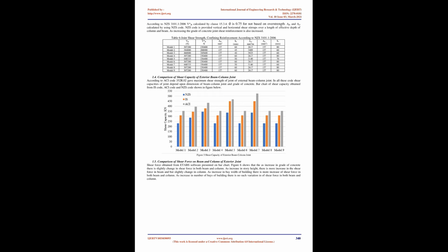Maximum shear force develops in model 7, which means shear force also increases with increase in story height of building. As bay width of the building increases, shear force is also increasing. There is small variation in shear force as grade of concrete and number of bays increase.